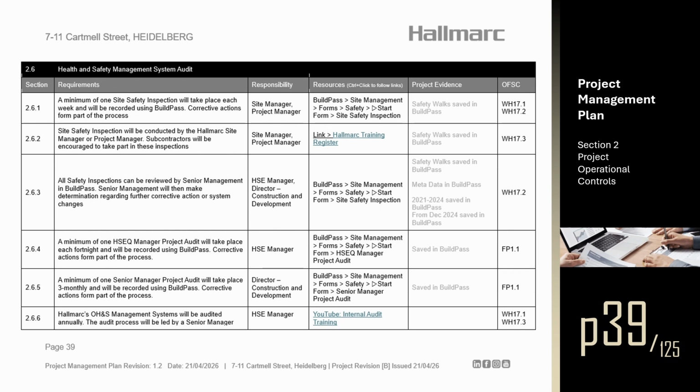Section 2.6. Health and Safety Management System Audit. Section 2.6.1. A minimum of one site safety inspection will take place each week and will be recorded using BuildPass. Corrective actions form part of the process. Section 2.6.2. Site safety inspection will be conducted by the Hallmarc site manager or project manager. Subcontractors will be encouraged to take part in these inspections.